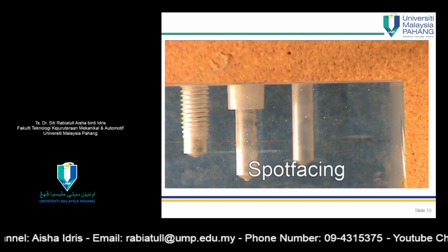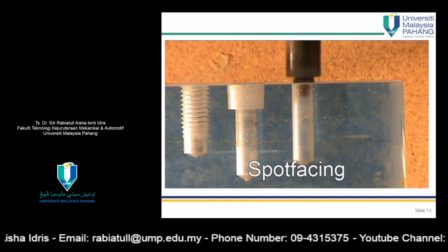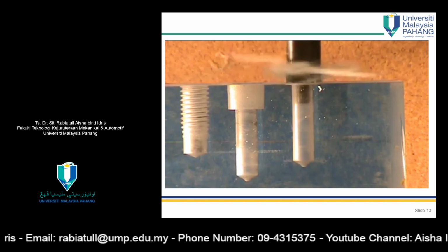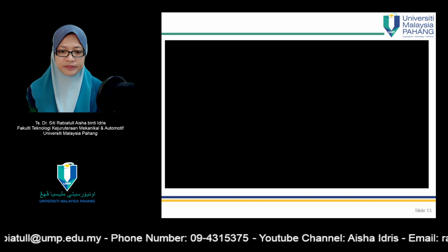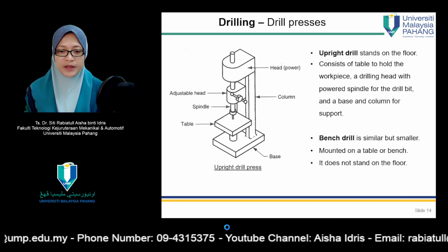Spot facing is used a lot of times on castings when the surface is uneven, to help the fastener sit down level on the top of the surface. Okay, that is spot facing.